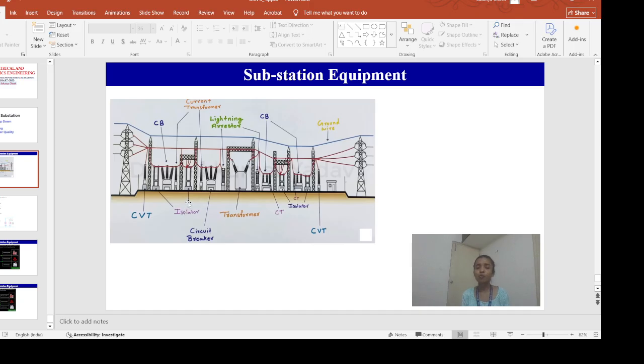So what the isolator will do is disconnect the faulty section of your electric circuit from the main supply. Now you can say that is what the circuit breaker was doing. But the circuit breaker's main function was, whenever the current was very high through the circuit, to make the current zero.